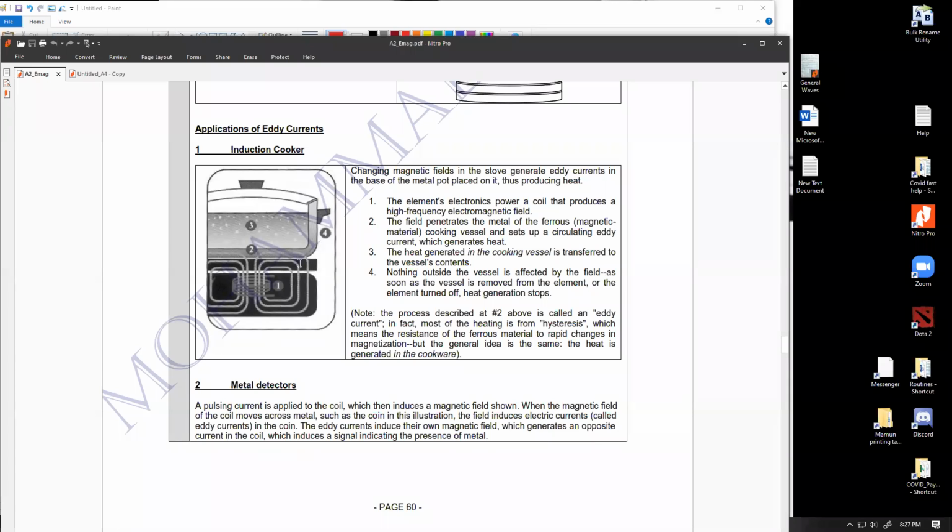The delta phi would be much weaker for the further part of the coil, which means because of the difference of the delta phi's, there will be difference of EMF generated, and this difference would be maintained as long as the AC will continue. So basically what's going to happen, electrons are going to continuously flow within this disk, radially outwards and radially inwards, radially outwards and radially inwards in the same frequency as the frequency of the AC supply. So do you understand my point?